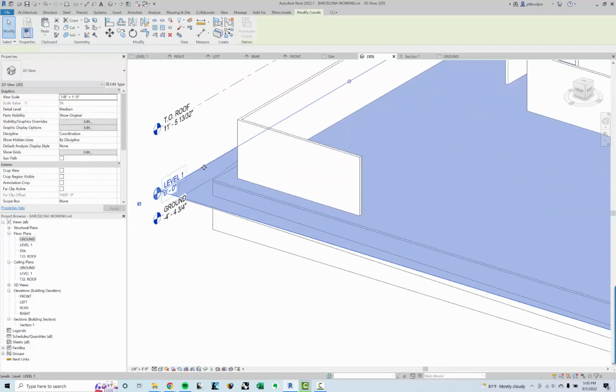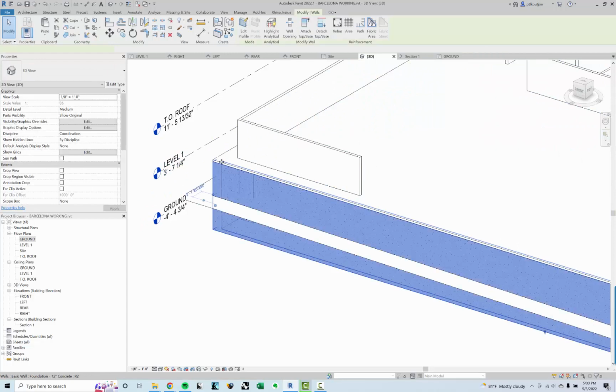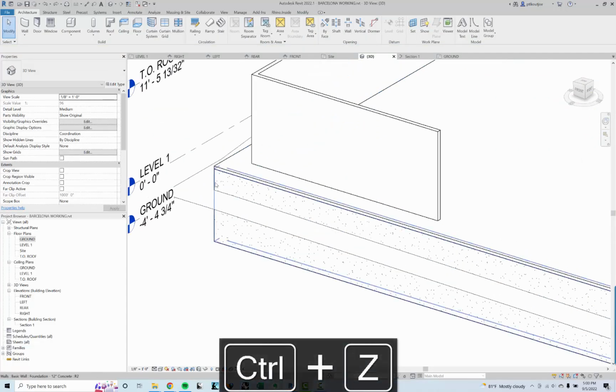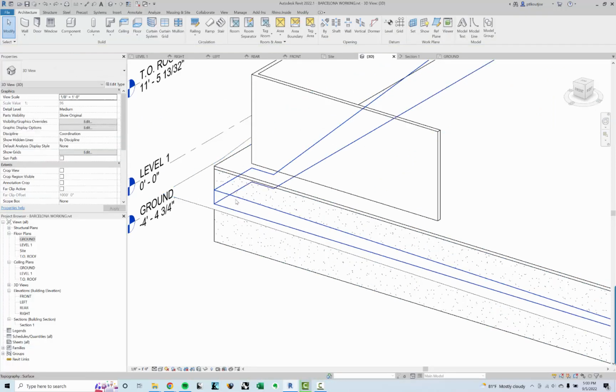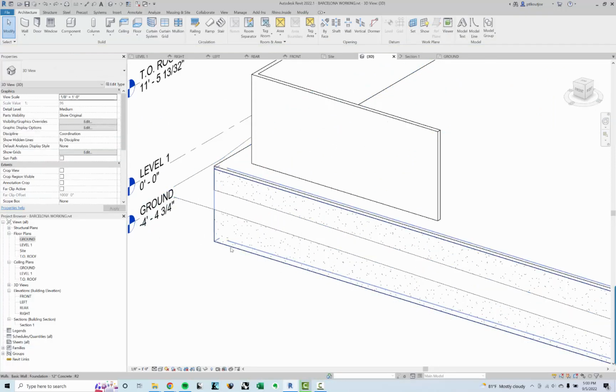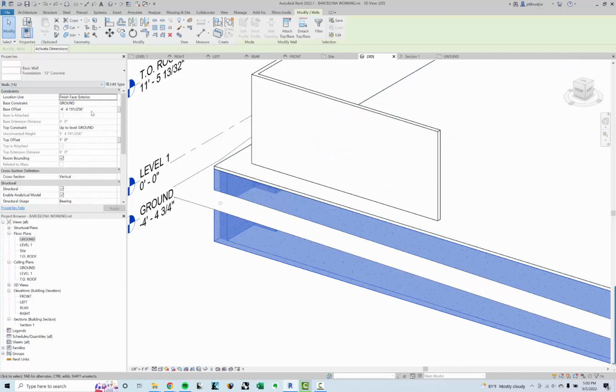And if this floor goes up, let me see. If I move level 1 up, that will be attached with it. If I want to undo that, I can click and go detach. But that's good. And then the last thing is I want this to be, let's just say, sitting on the ground for now. So let me set this as 0.